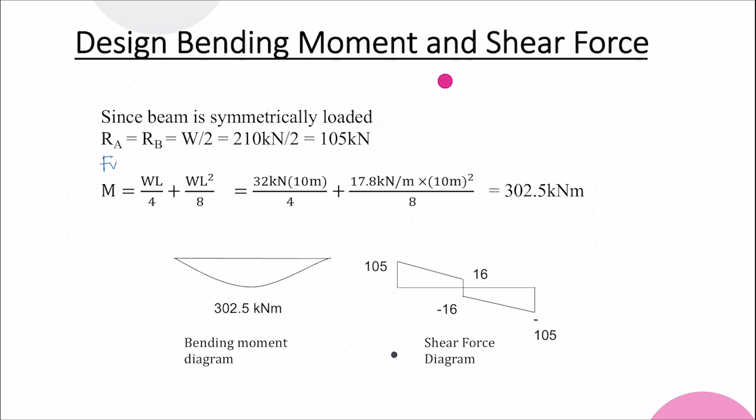So, in order to do so, normally if we want to get the shear force, we have to draw the shear force and bending moment diagram. So, when you have UDL and point load together, combined, L over 2, meaning the midsection of the beam. So you will get something like this for shear force. Okay, and the bending moment diagram, you will get something like this.